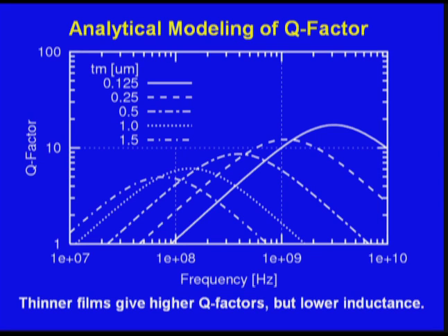So if you keep your eye on this thicker magnetic material, in this case 1.5 micron, it's this dot-dash line. In the next slide, I'm going to replot this line as a solid line, and then I'm going to plot other lines that were calculated for the ideal case where the magnetic via just wraps around the magnetic material. I forgot to mention that. That's what this analytical model was doing. It doesn't look at what's going on in the actual via if you have these wing-like structures.